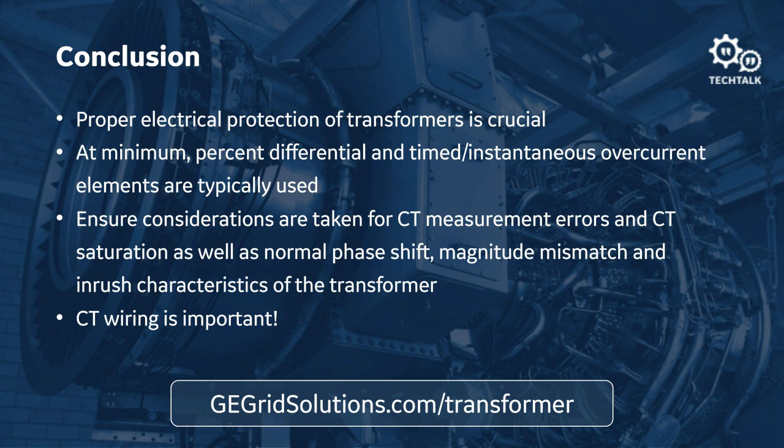You have your CT ratios. You can refer to the user manual to get the magnitude and phase compensation formulas, calculate the values for each phase, find your differential and restraint currents, divide them and see whether that value falls above or below your dual slope characteristic, which you might need to plot to figure out.